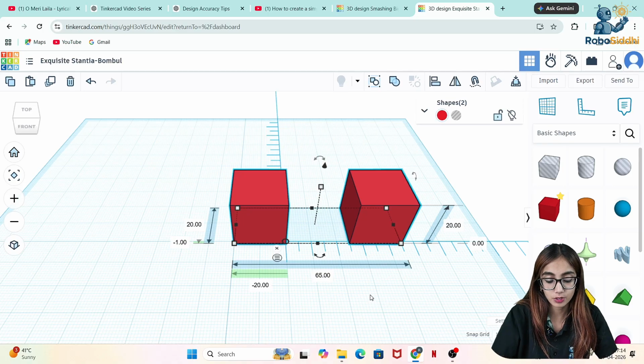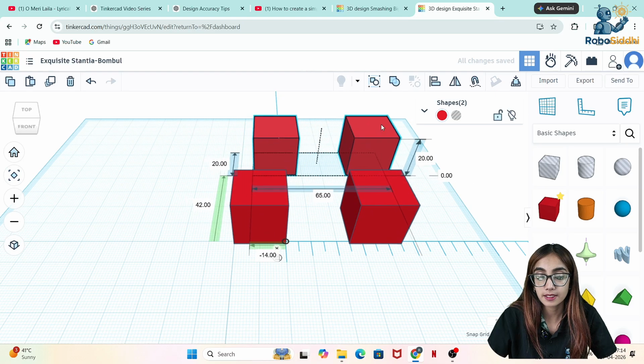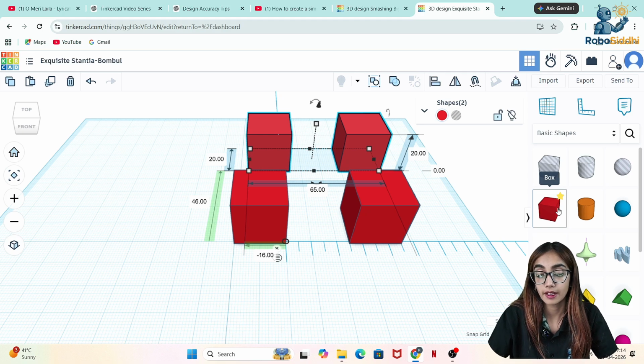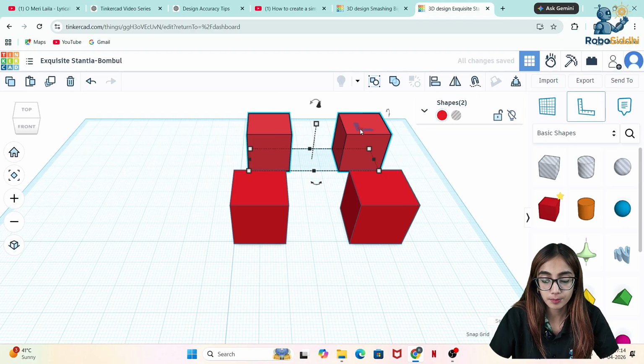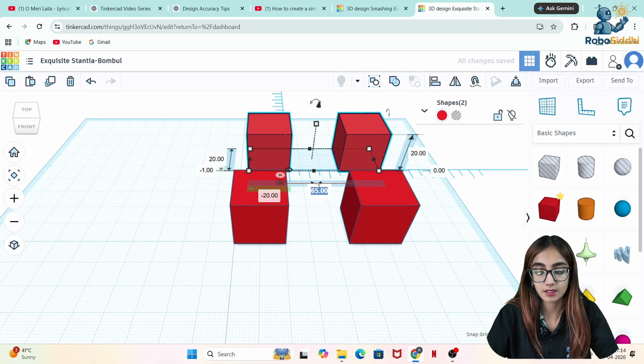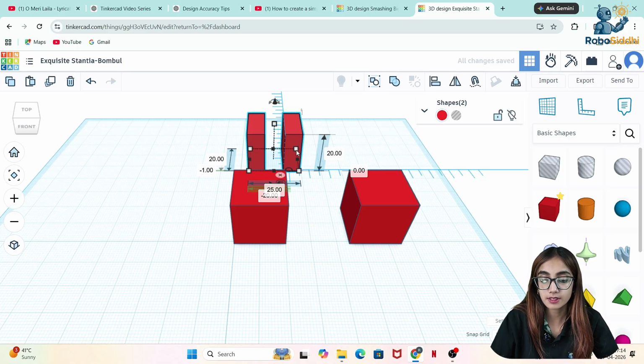select both of them and just copy and paste, I'll get another set of parallel cubes, which I can place just behind them, right? So I did not have to drag another two cubes and measure their distance. Okay, so this is how it helps us. Now if I simply place the ruler tool over this distance, I'll make this say 25 millimeters again. Okay, so this is how it works.